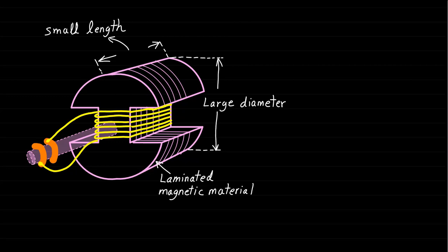Synchronous machine that uses salient pole rotor type is usually used in low-speed applications such as hydro generator. Synchronous machine that uses salient pole rotor type cannot be made strong enough to withstand high speed. Also, salient pole machine would cause excessive windage loss at high speed and would tend to produce noise.